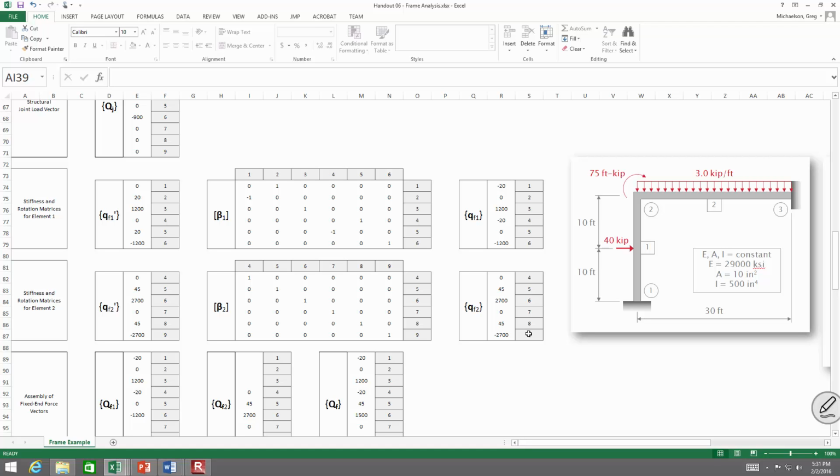This first one is a beam with a point load at center. Based on that, I can determine my reactions and end moments from the fixed end force tables that you all have been handed out, right? Now, I rotate that, however, to get global fixed end forces.